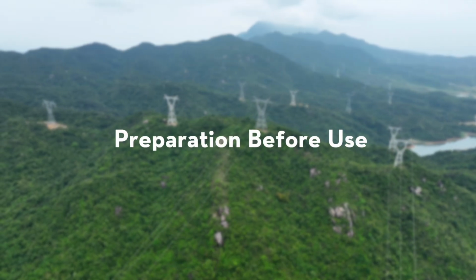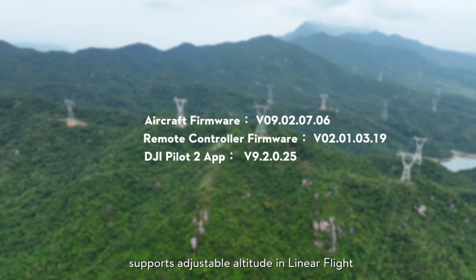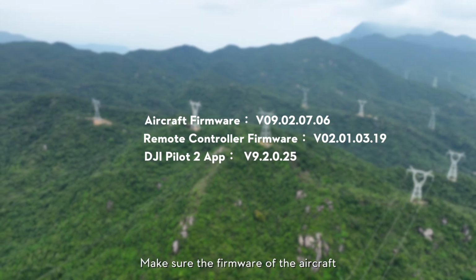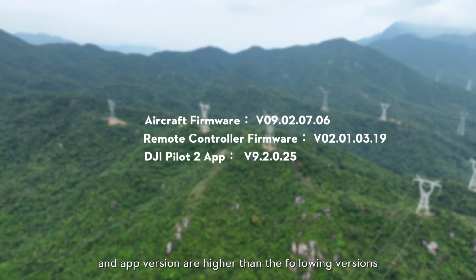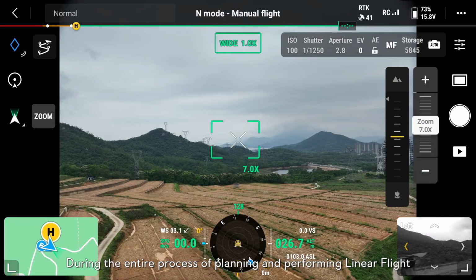Preparation before use. The latest firmware of DJI Mavic 3 Enterprise series supports adjustable altitude in linear flight. Make sure the firmware of the aircraft, remote controller, and app version are higher than the following versions. During the entire process of planning and performing linear flight, make sure RTK is connected.